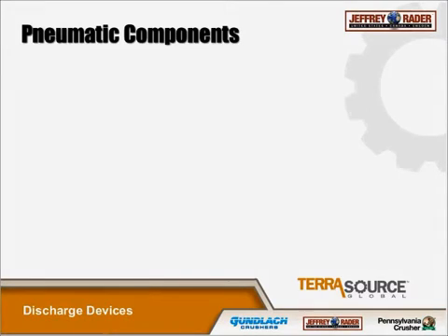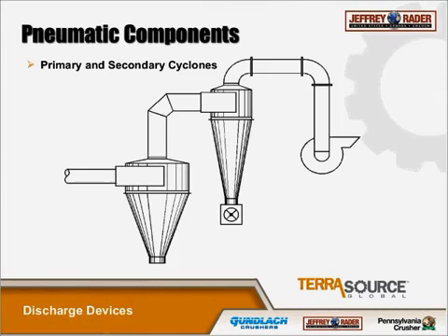Sometimes you have environmental concerns where you don't want to release the air to atmosphere, and in this case you can have it released to a cleaning device, or in this image, a secondary cyclone. So there's the primary, and then there's the secondary cyclone.